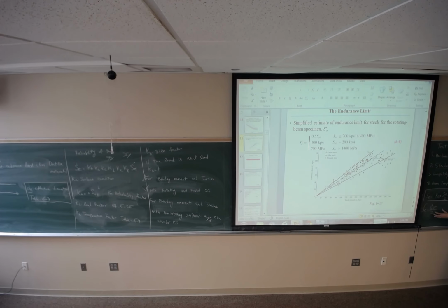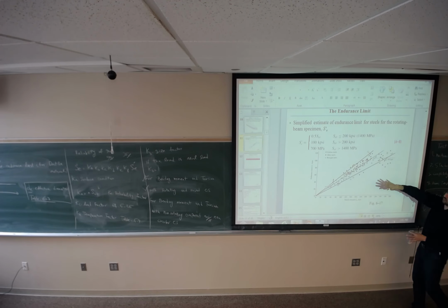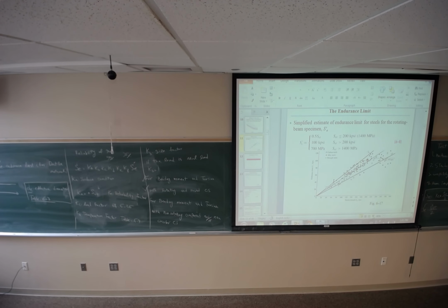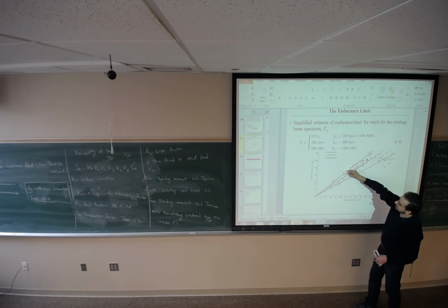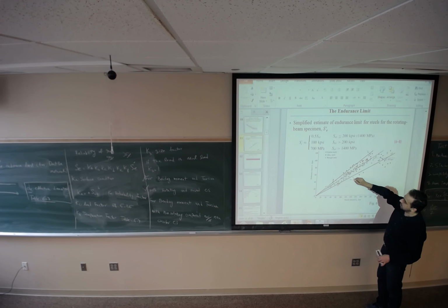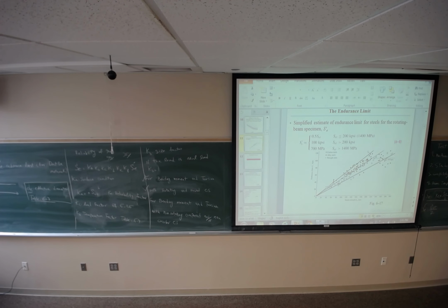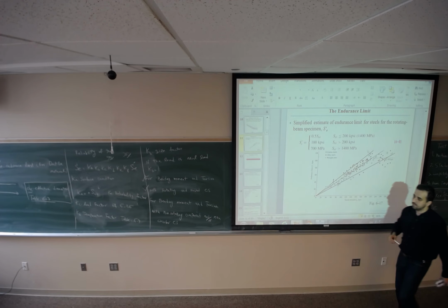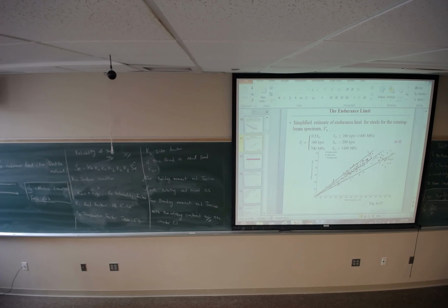So what I'm saying is this equation has 50% reliability. If you want to be more reliable, then you should consider this factor. Because I showed you, for example, for this point, you expect, based on this equation, to have this amount for S prime E, but in reality it's going to be much lower than that. To address this issue, we introduced K. Okay. 50%. That'll work out.